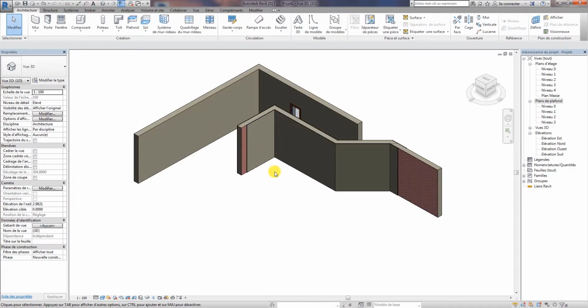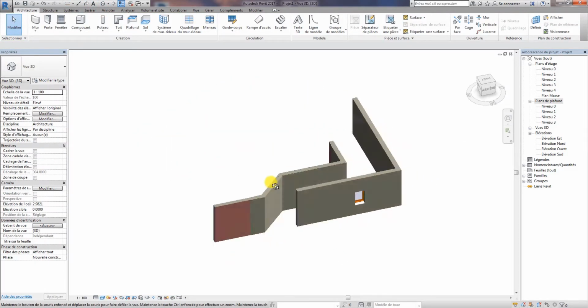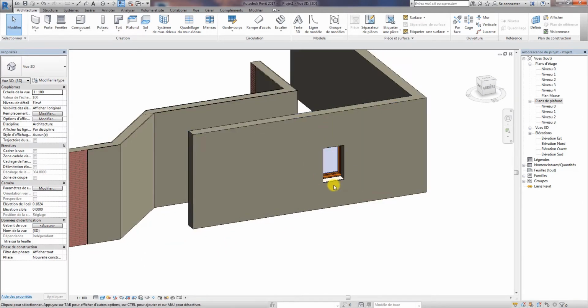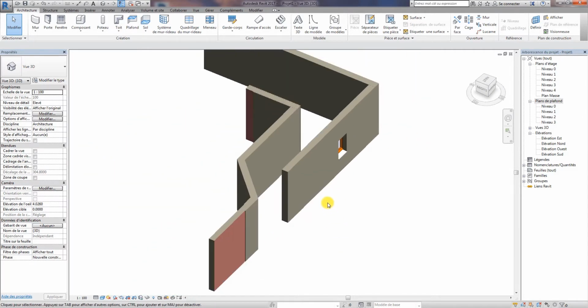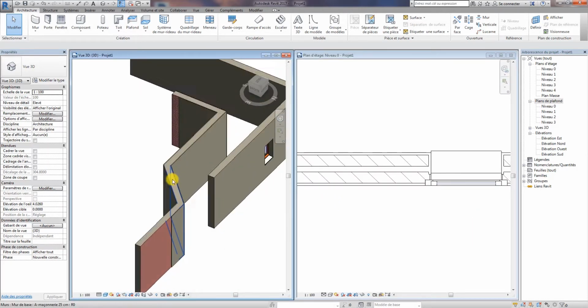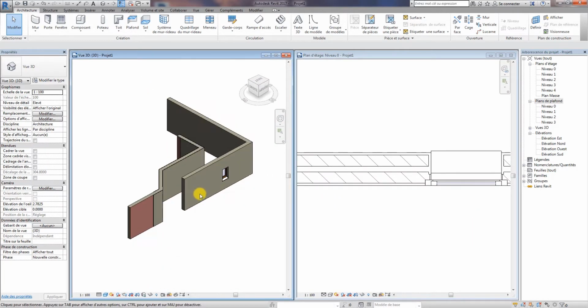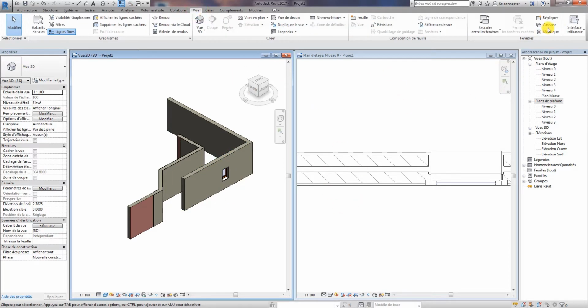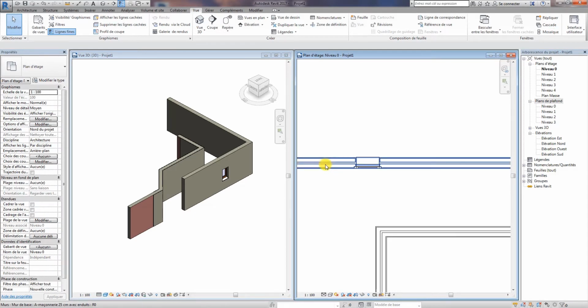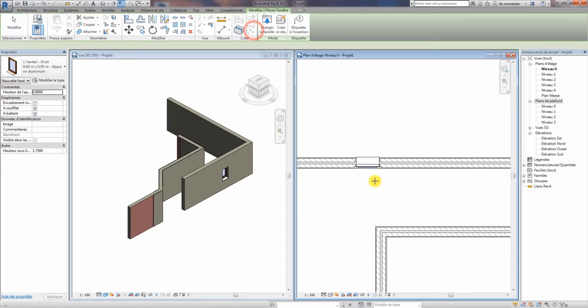Click on the little house icon to take you to the 3D view and examine the result. Now type WT to tile the two windows already open in the Revit session. This can also be accessed through View, ribbon, and then Tile.